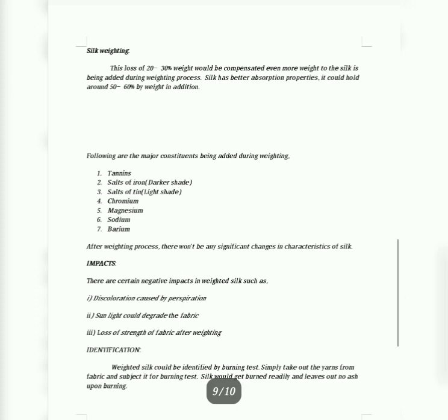And the next, carbonizing. Sometimes scouring and carbonization are similar. Sometimes scoured wool contains vegetable impurities that cannot be completely removed through mechanical operation. Sulfuric acid is the chemical substance used for destroying the vegetable particles, and the process is called carbonizing. This process is done at the last, similar to scouring.